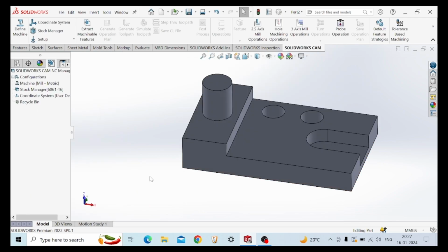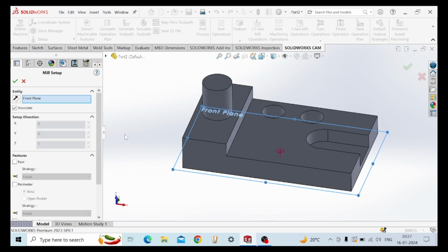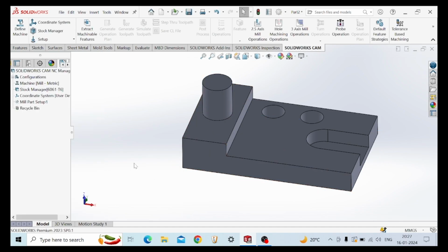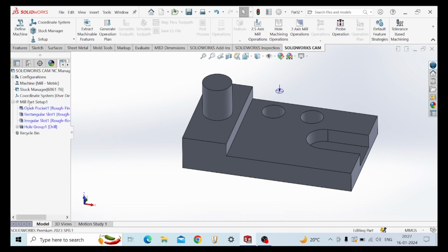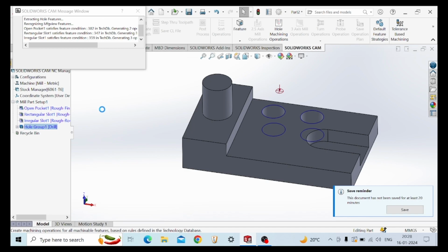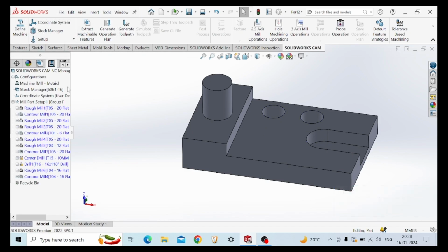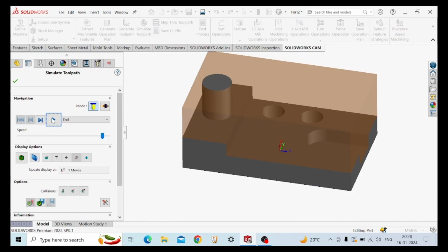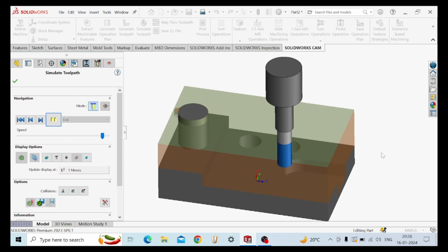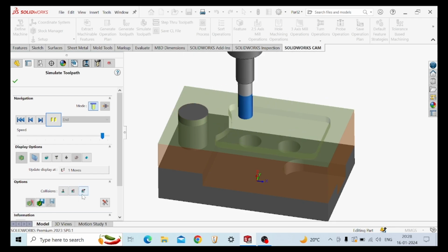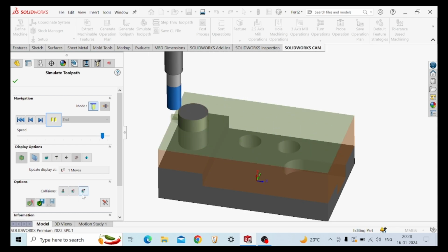Now this is the stock material application, from which now there is the milling operation. So I will select the topmost face, and see, it has generated the code. Okay. So now this is toolpath generation, the path that it is going to follow, and now this is the ultimate simulation. Okay, how the milling operation will be done and how these features will be embedded on the job.